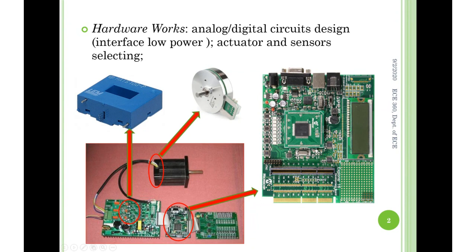There are some buttons here for different physical analog inputs. And this is the typical encoder. Obviously, again, not the same thing; I'm just giving you an example encoder here. From it you can receive the position information. The encoder we always use nowadays is the QE, where Q represents quadrature encoder.